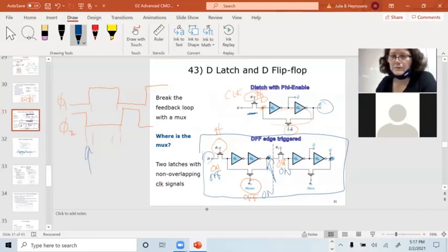So is the purpose of the double inversion just to add a bit of delay to the system? It's part of the latch. It's part of the storage, because when phi is off, I have that back-to-back inverter in there, and it reinforces. If I have a 0 here, I get a 1 here, I get a 0 here, 0's fed back. So it's adding some feedback in there that reinforces and keeps the signal low or keeps the signal high, even if I don't clock it or don't enable it for a long time.